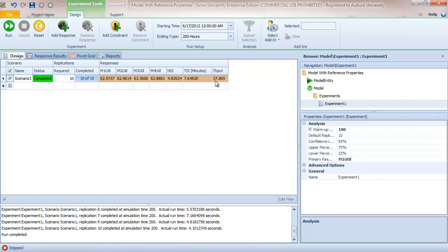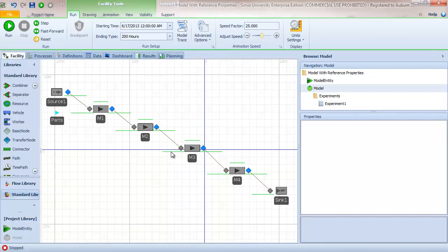So we have recovered part of that lost capacity at the expense of additional time in system, and additional parts in the system at steady state. So clearly what we'd like to do here is compare the performance metrics, in particular the throughput, for different values of input buffer size. So we've seen 0, now we've seen 1, and we've seen infinity, and what we'd like to do is explore that further.